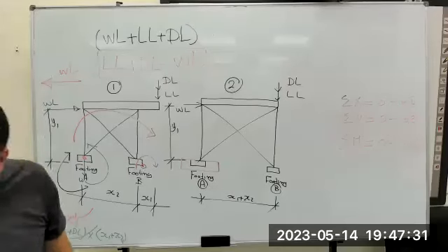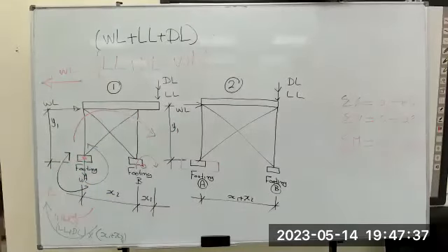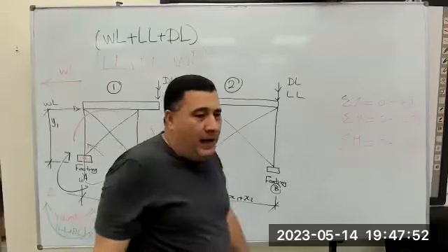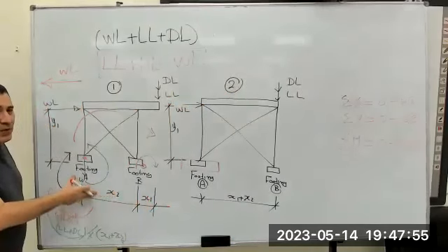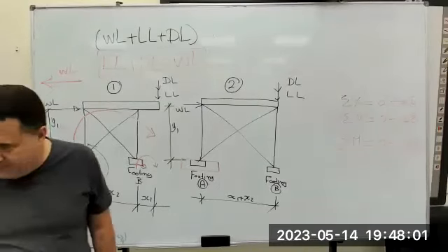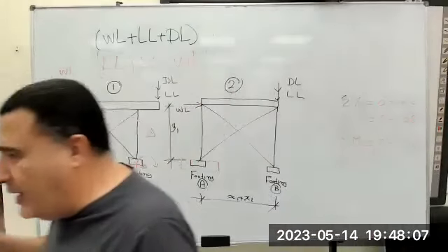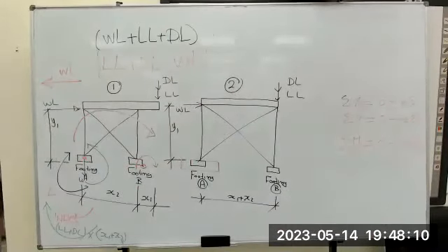Why not? We are in the building and there is a particular force, it could move this building to the next road. So all the forces should equal 0 in the XY direction, and the moment at any point should equal 0, to avoid the 3 effects: overturning, uplift, and sliding.